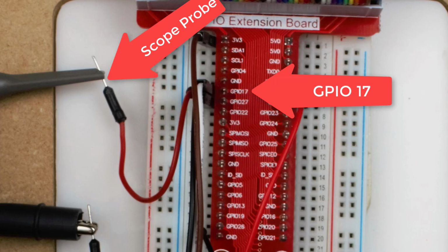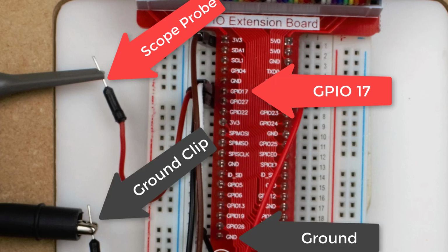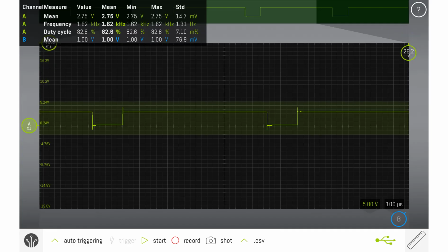And then we will clip the oscilloscope probe to the other end. The other point that we will connect to is ground. You can get the ground anywhere. I've just got the ground down there at the bottom on pin 39, but any ground would be sufficient. And then I clip the ground lead on the jumper wire.